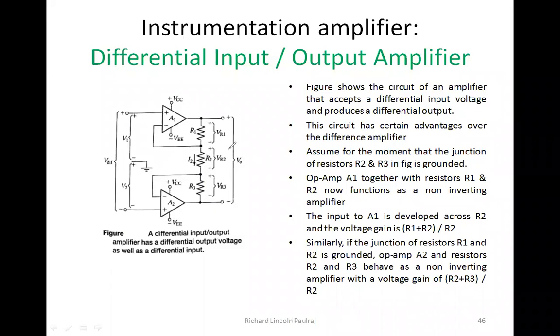We were seeing that this resistor is actually playing a very major role in controlling the levels of outputs between both of the op-amps. So that's important. And we were also looking at resistors R1 and R3, and how these resistors are inside the feedback. We also saw the junction between R2 and R3 is this point.